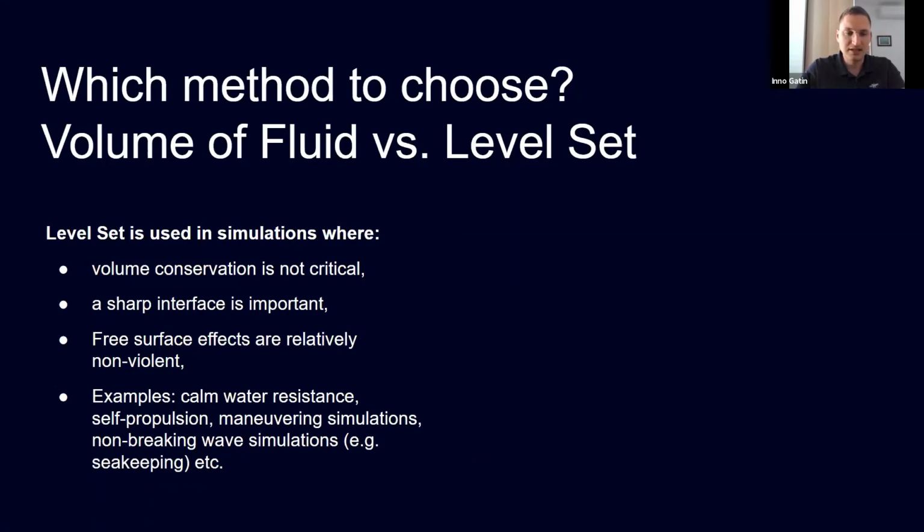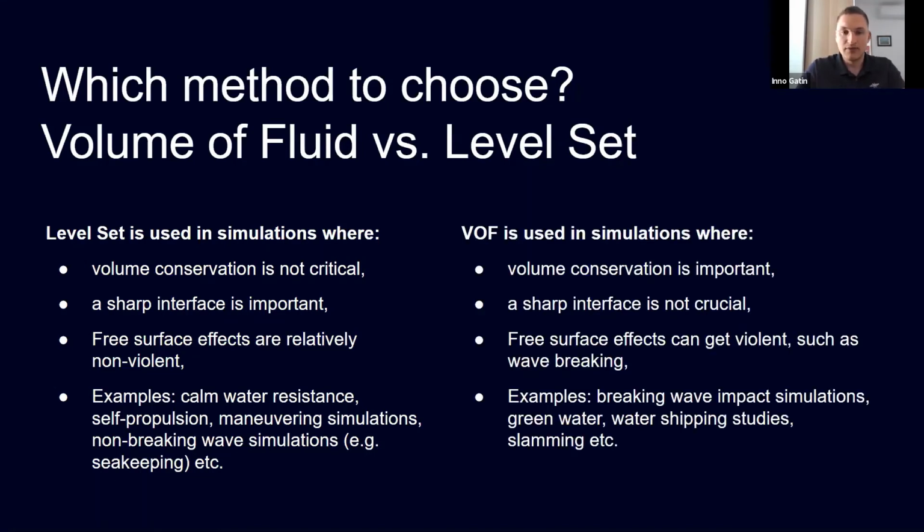So as I said, examples are calm water resistance, self-propulsion, maneuvering, also simulations where you have non-breaking waves, such as seakeeping in relatively mild wave fields. VOF, on the other hand, you will use when volume conservation is very important, but where you can live with a little bit of smearing.